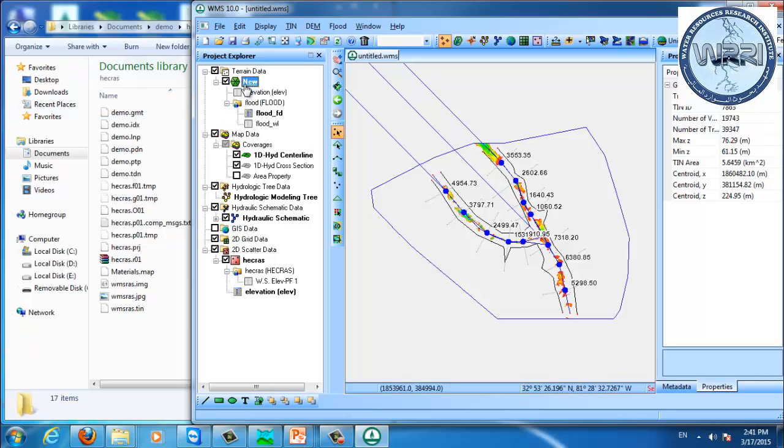Sometimes when I get this floodplain, I find flooding very far from the main stream or main channel, and there's no way for water to get there. You could try decreasing your search radius. If you decrease your search radius, you might not have that happen. Yes, I tried many values. I remember that I changed this value until I got a good result, because all the time I found water in some places where there is no water. That's why I asked about this.